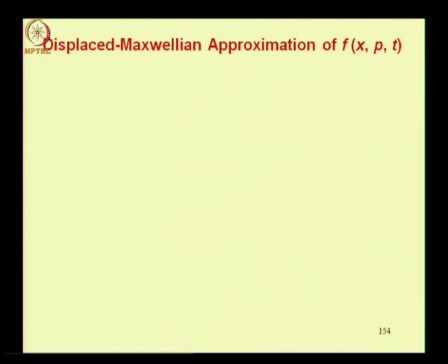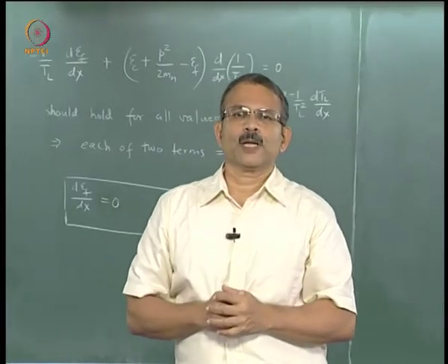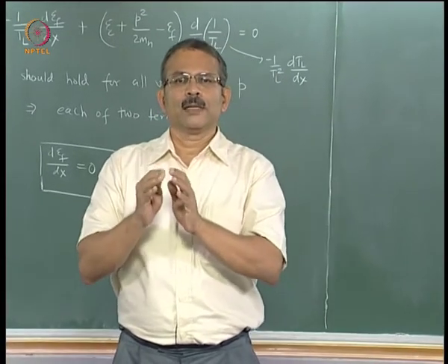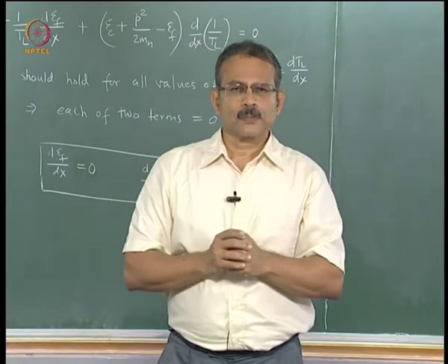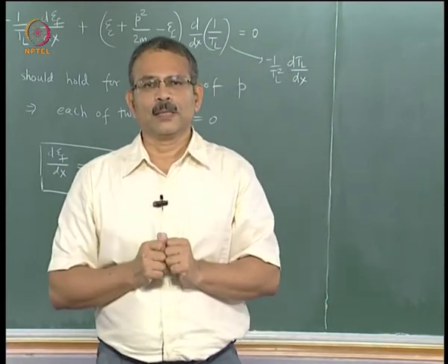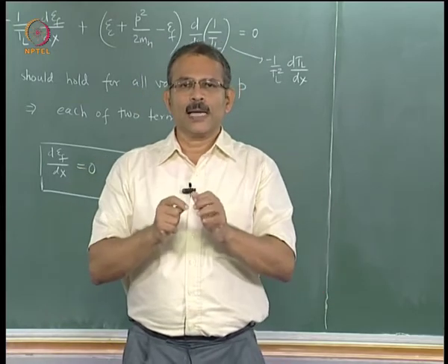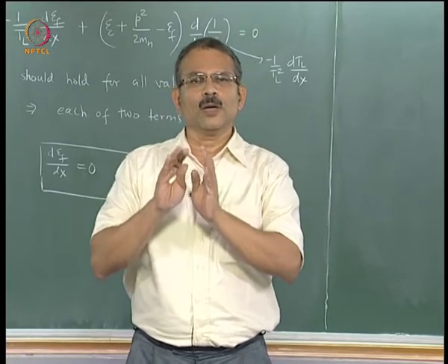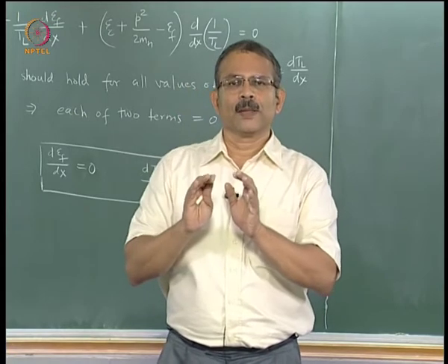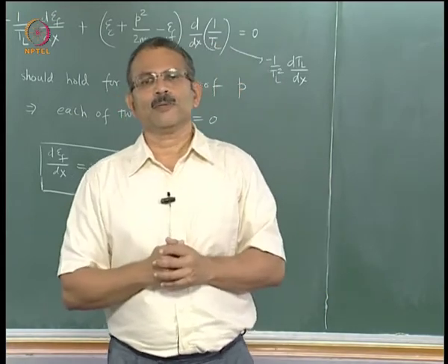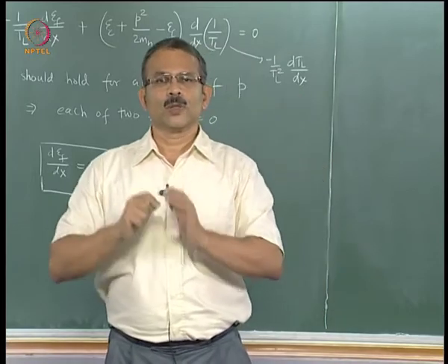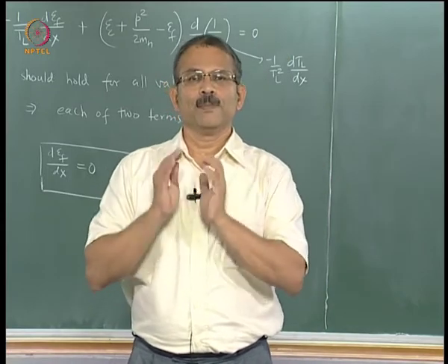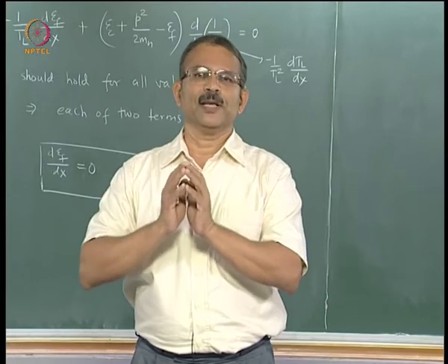Now we said that one approach to solving the Boltzmann transport equation is to take the equilibrium distribution function and perturb it to accommodate the happenings of the non-equilibrium case. So what is happening in non-equilibrium? We know that under equilibrium the entire carrier population has no net motion in any direction, or no drift velocity, or in general no directed velocity, because your current could be because of drift, diffusion, thermoelectric current, anything, right. So let us say directed velocity. Under equilibrium there is no directed velocity, or there is no momentum p, right, average momentum p is 0.